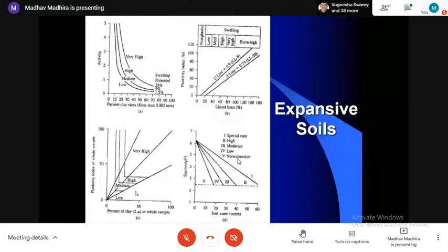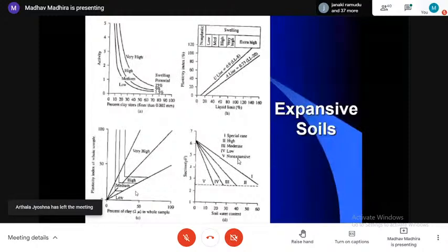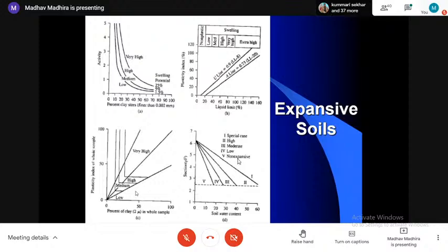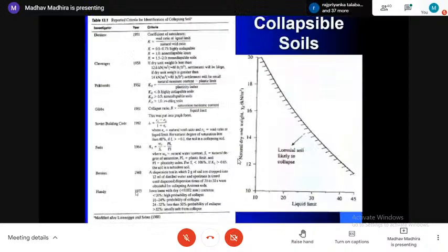So what I'm now trying in my practice is that I try to keep the water away from the soil by proper drainage measures or surface measures wherein water does not enter into the building site or near about it, then I have no problem at all. So then we don't have to worry about black cotton soil.